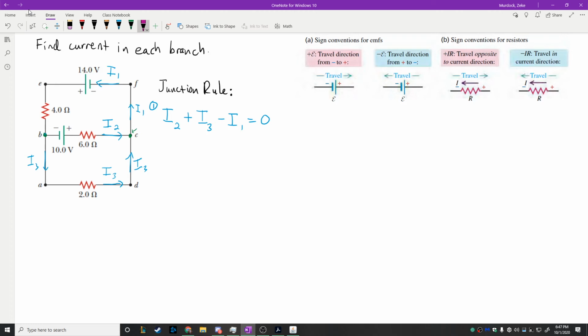A junction is any point where there's like a T. You need to have at least 3 lines that cross each other to have a junction. If I have just 2 lines like a corner, the corner doesn't mean anything, right? Because these are wires. Remember, these are wires, okay? So the wires, in a real circuit, they're not going to look like this. It's just going to be wires. They bend, okay? But this point is a junction because you have at least 3 lines that are connecting there. You need 3 or 4 or 5 lines connecting together.